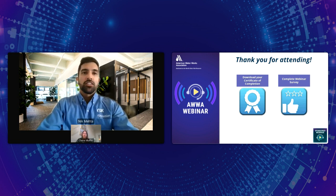Whether in every application you are going to get credit for 5 logs, I think there's a difference between we can technically prove a 5 log reduction and whether you will in every state or every application actually get a 5 log credit for it. It is a new technology. We're still working with regulators to prove that the membrane integrity test is valid. We need to separate it in people's heads from ultrafiltration in that regard, so that we do get the credit for log removal that the membrane actually does achieve.